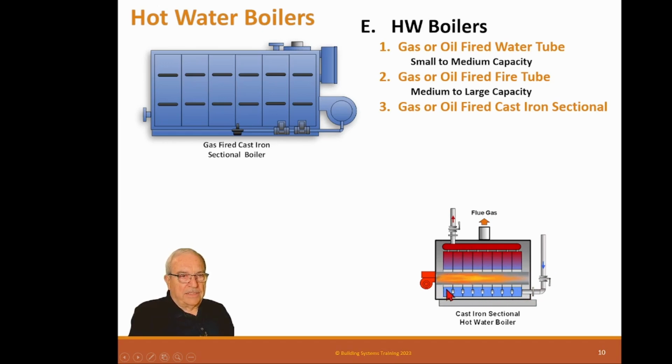And then as the water heats as it goes up here, it's connected again into this hot water tank, and it goes out. So this one becomes much like the fire tube, except it's not got fire tube. The fire's in these cast iron sectionals. And the reason these work good is the cast iron absorbs a lot of heat. So once you get one of these hot, you don't have a lot of flame variation because these retain heat in this cast iron, which then actually heats the water.